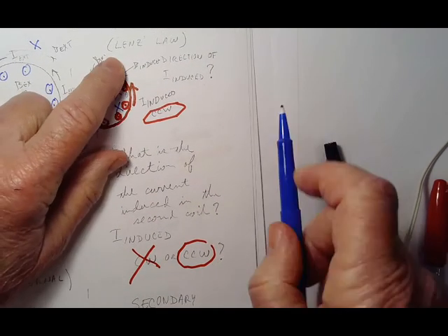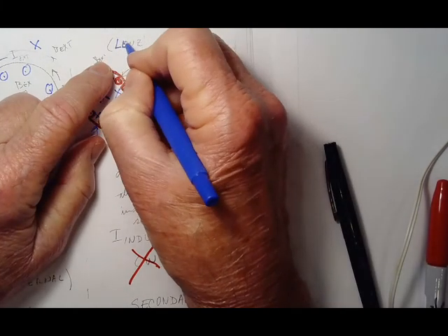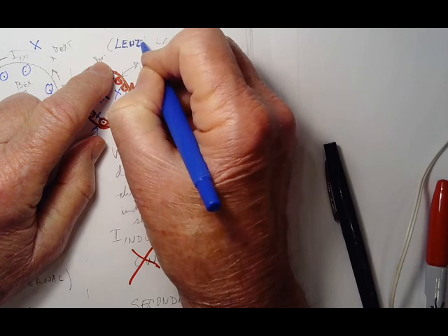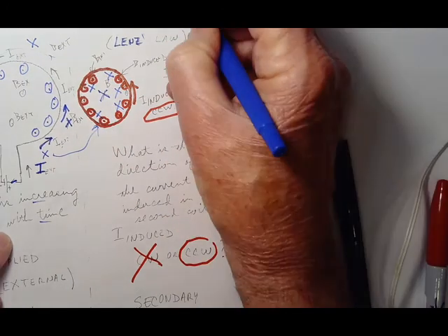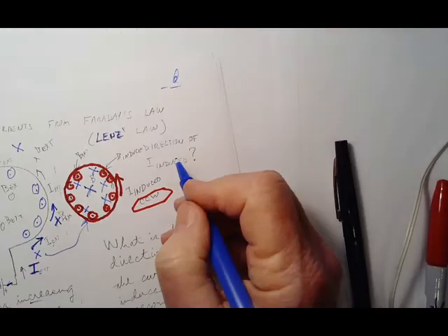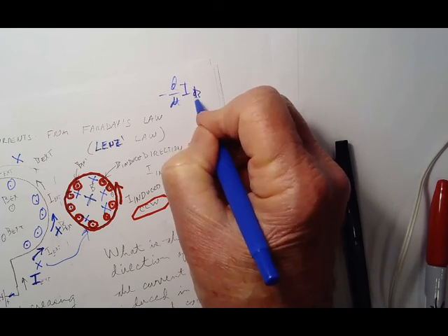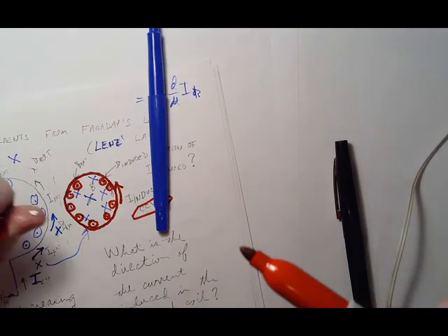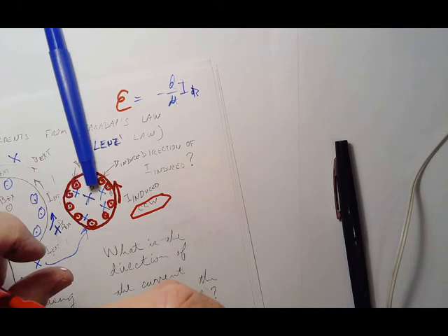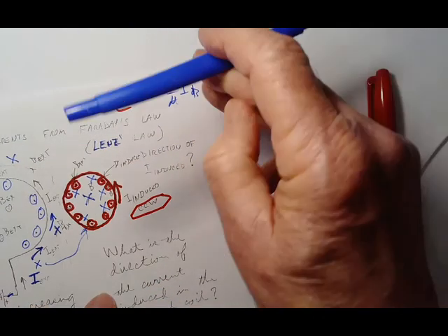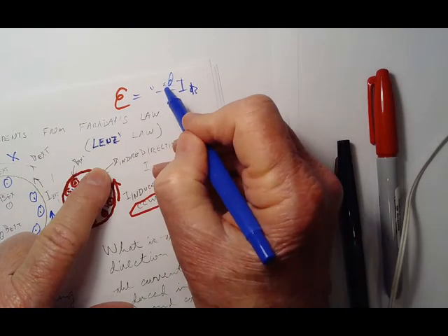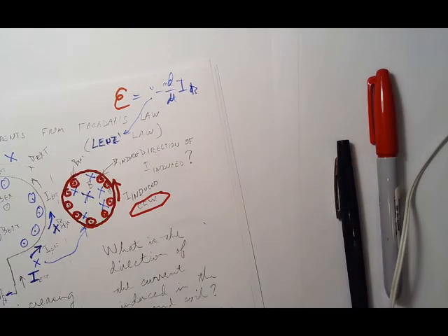Faraday's law, Lenz's law, another word I told you for Faraday's law, having to do with that minus d phi sub B dt, that's epsilon, EMF over here. That little minus sign is the part of this thing that is sometimes called Lenz's law.